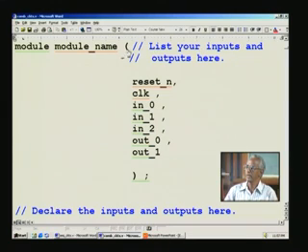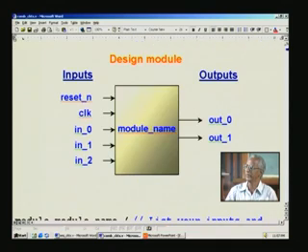And here note that there is a bracket here, it starts there and ends here, followed by a semicolon. Do not forget the semicolon or the brackets mentioned here, and you have already seen this line comment. So, you can freely use the line comments just to explain what you are doing in any part of the design. And here what you see is a list of the same IOs that we have already seen in this block earlier, these things plus the outputs.